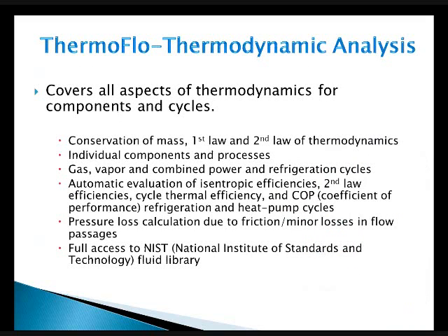The thermodynamic analysis, which you're going to go into quite a bit more detail later on, Ben's going to handle this side, allows for solving for the conservation of mass and first and second law of thermodynamics. It's made up of individual components and processes that can be put together in a system, and it solves gas, vapor, and combined power and refrigeration cycles, while automatically evaluating the isentropic efficiencies, second law efficiencies, COP, for refrigeration and heat pump cycles.